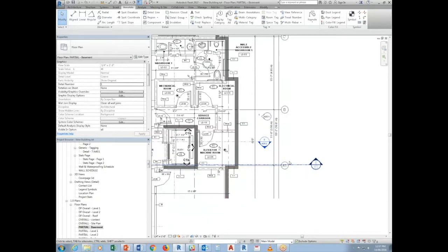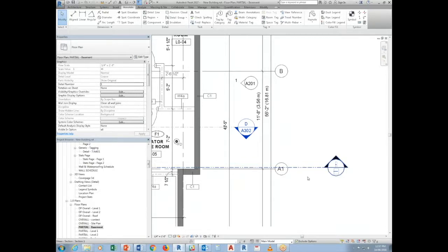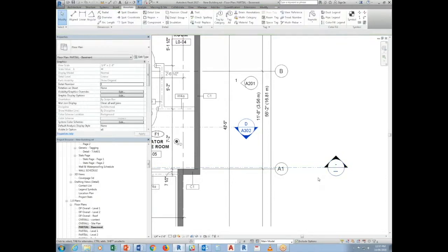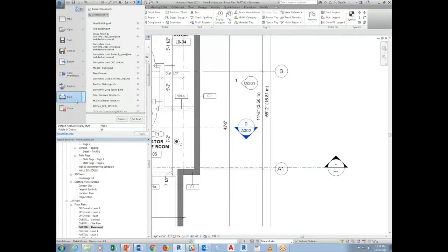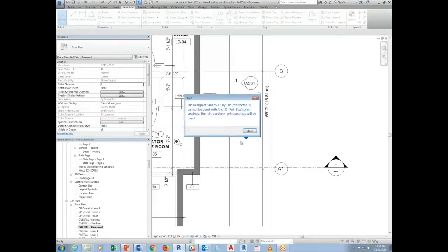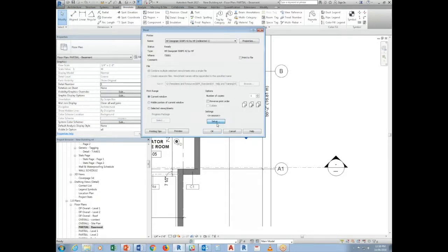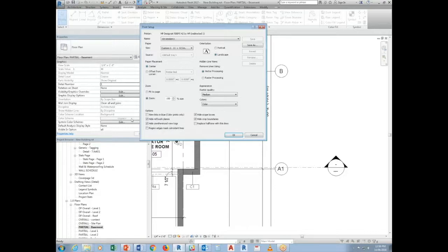And also, if you want to hide certain things, I know that when I look at the template, some of the unreferenced view tags get hidden, which I find very strange. The reason why I say it's strange is that you don't have to do that, because when you start printing, when you go to setup, you notice that there is hide unreferenced view tags.